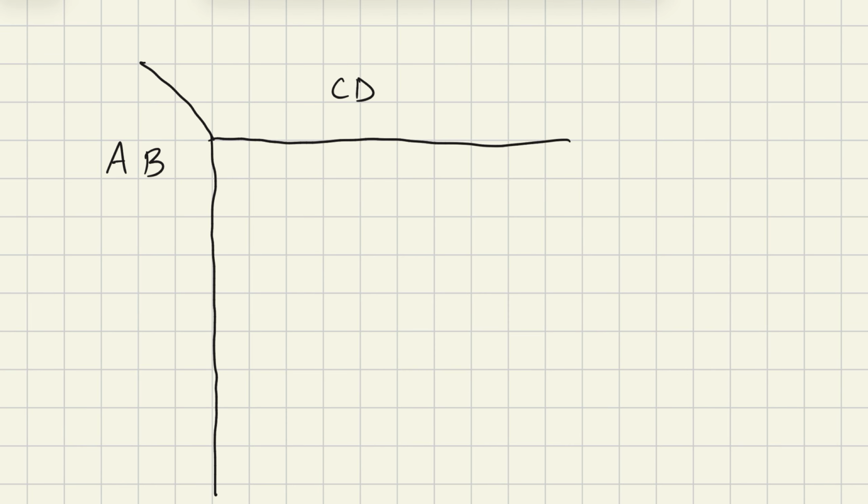The first step would be to draw the outsides of the K-map. So to draw a 4 variable K-map, we know that we can have 2 variables on one side and the other 2 on the other. So we can put A and B over here and C and D over here. And then we can simply draw the outsides. And just like before, we want to consider all the possible scenarios that each of those variables can take on for the outside of the K-map.